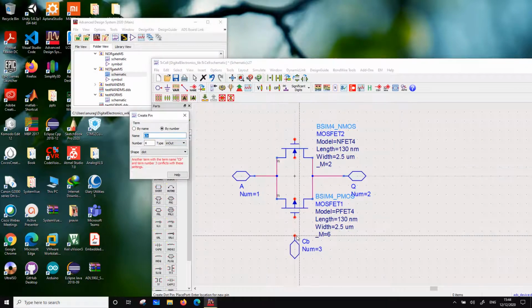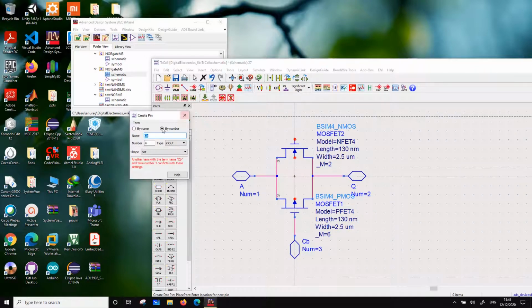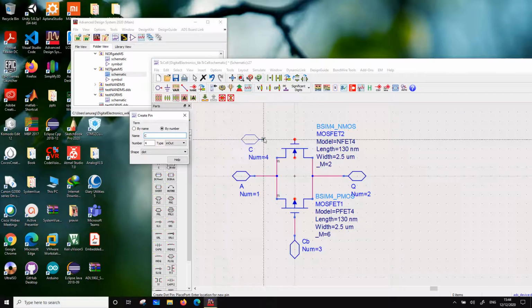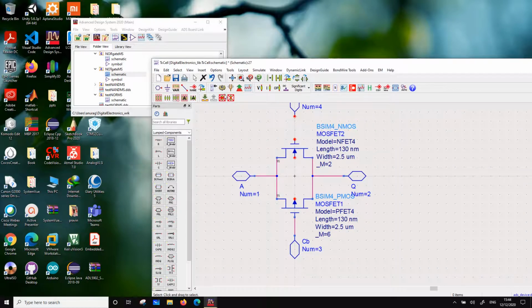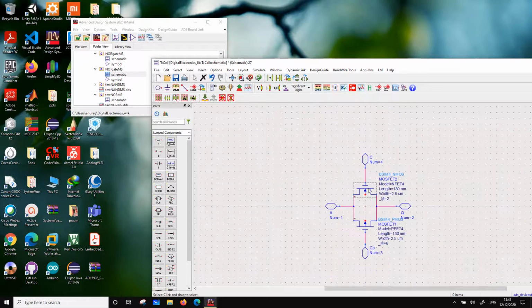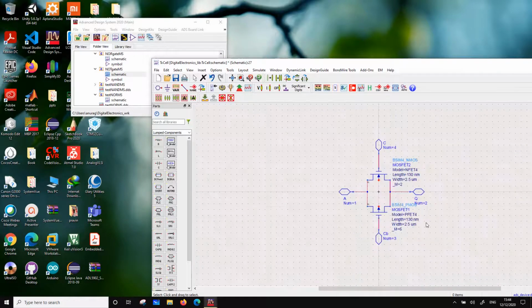So 1 will be transmitted if control bar is low. And the other side is going to be C, the control signal. So the NMOS will be on when the control signal is high. Right, so if C is high, then 0 will go through. So this completes it.